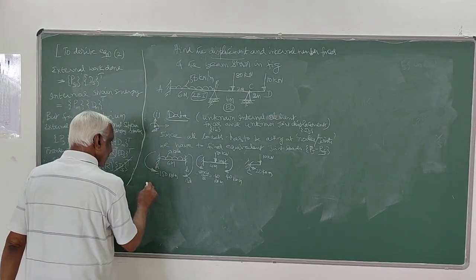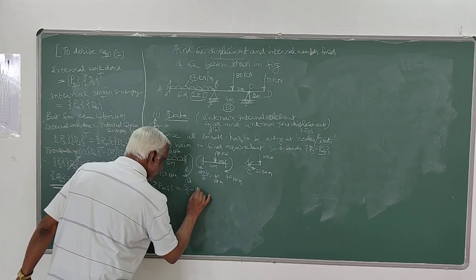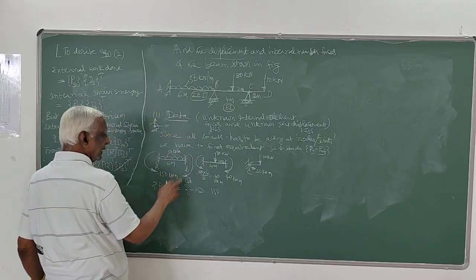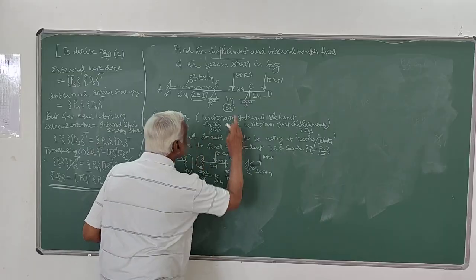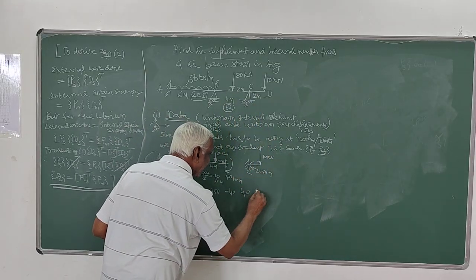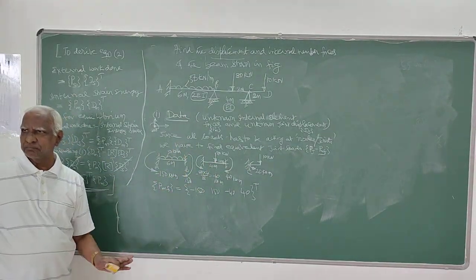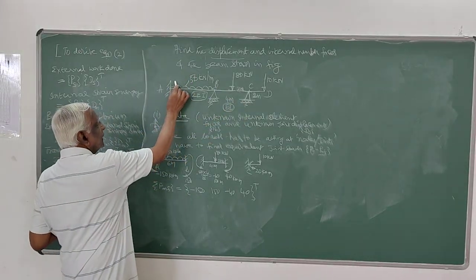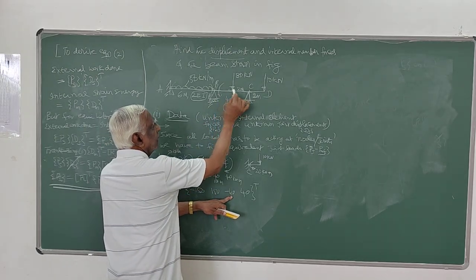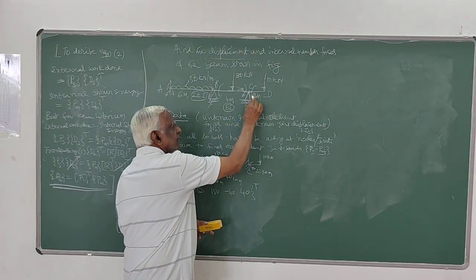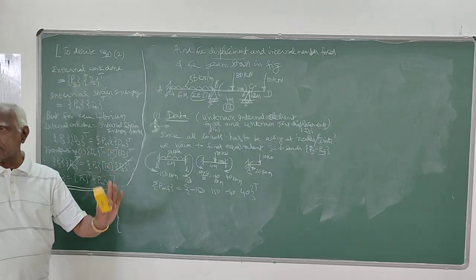Therefore, now your PMS, the fixed end member actions, will be: MAB is minus 150, MBA is plus 150, MBC is minus 40, MCB is plus 40. And this CD, of course, you need not bother, it will be the overhang portion. It is anticlockwise. In the regular members, the member end actions are: here minus 150, here plus 150, here minus 40, here plus 40, here of course it is 20. Any doubt? These are the fixed end actions, not allowing any displacement.